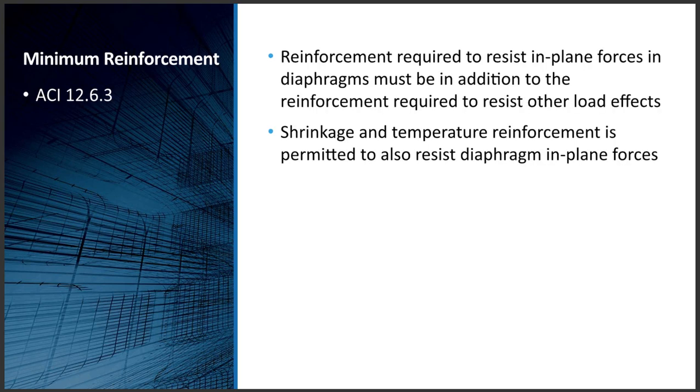Just another couple things to keep in mind, and we discussed this in our previous sessions: any reinforcement that we need to resist the specific forces that are resisted by the diaphragm has to be separate from any other reinforcement that's in there, with the exception that we are permitted to use this shrinkage and temperature reinforcement to resist some in-plane forces.